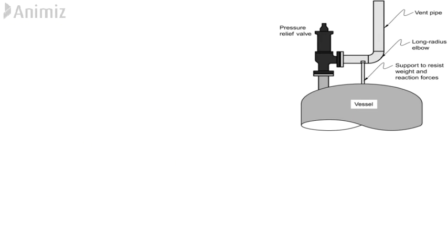Second case, the percentage overpressure of the safety valve is greater than the percentage of maximum allowable accumulation pressure of the system. In this case, making the set pressure equal to MAWP means that the relieving pressure would be greater than MAAP, that is the maximum allowable accumulation pressure, so the set pressure must be lower than MAWP. Let's see what it is.